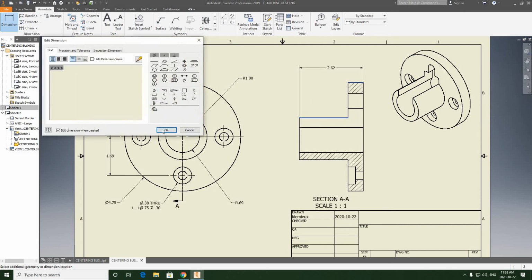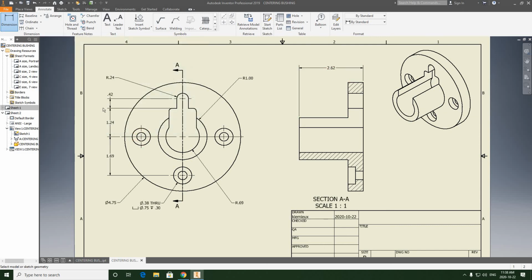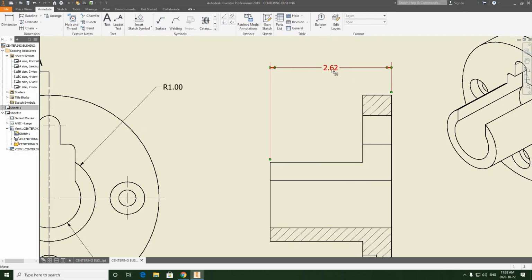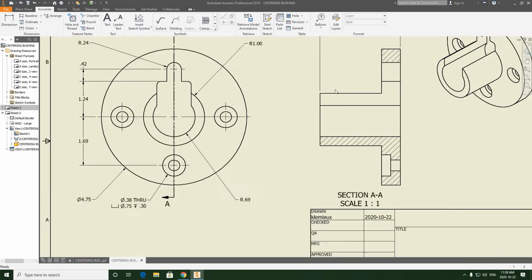Keep my spacing consistent, right? The spacing I see from here to here should be consistent from here to here. We shouldn't have dimensions that are way too far away or way too close. Remember that little gap indicator kind of helps you, right? You're running your dimension, you see it go broken. That's a guide to kind of keep you on the right track.